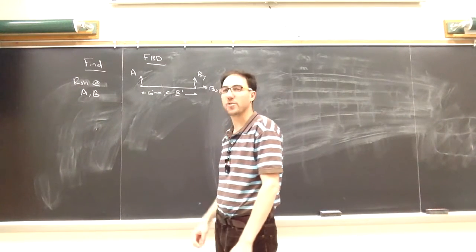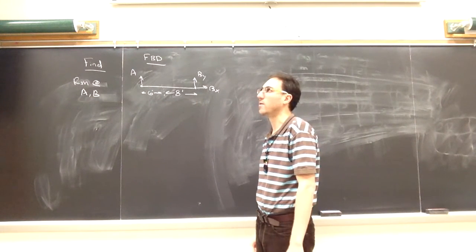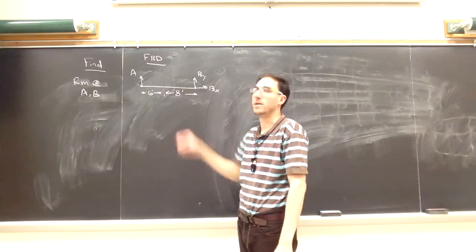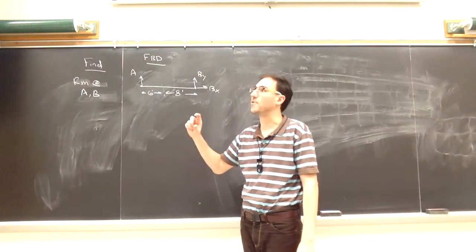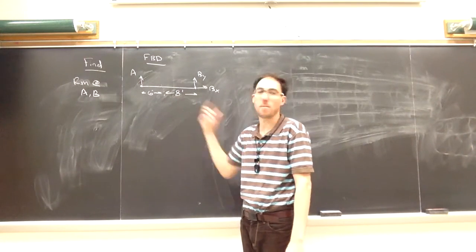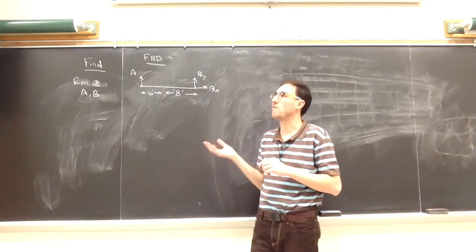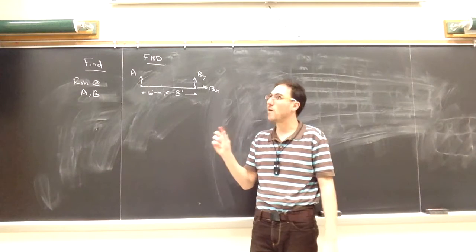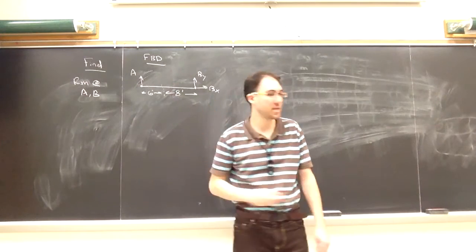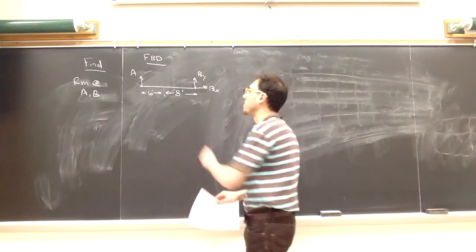So what I can do is treat it as two different shapes. I'll start with the easier one, the rectangle. We see that the intensity of the rectangle is 150 pounds per foot. So we can treat that like the height of the rectangle, 150 pounds per foot, and its base is 8 feet long, where we're applying this load. If we find the area of the rectangle, 150 pounds per foot times 8 feet, the area of that shape will give us the equivalent force due to just the rectangle. So 150 pounds per foot times 8 feet is 1,200 pounds.